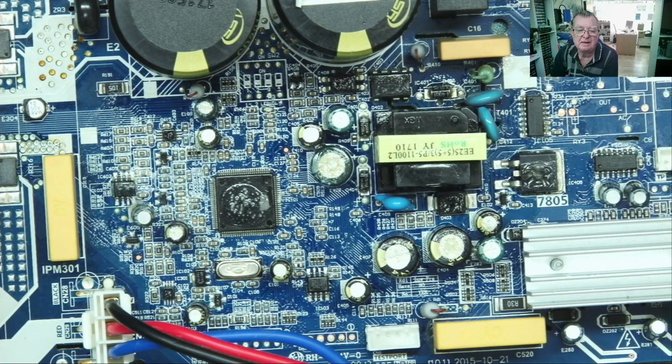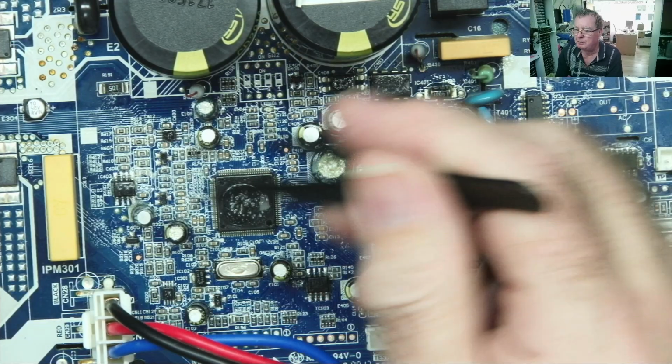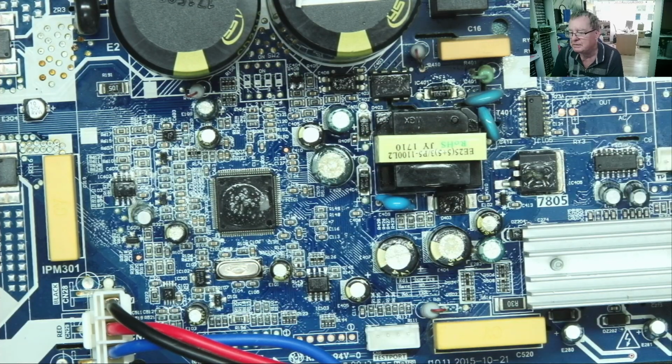And this is where I would call it not a proper fault. So although the device won't work, you cannot diagnose and repair this by poking around, even knowing what you are doing with your multimeter. Because at the end of the day, there is nothing wrong, really. All the components are okay. It's just the contents of the EEPROM or the flash memory built into the microprocessor, microcontroller, that's faulty, it's corrupted.